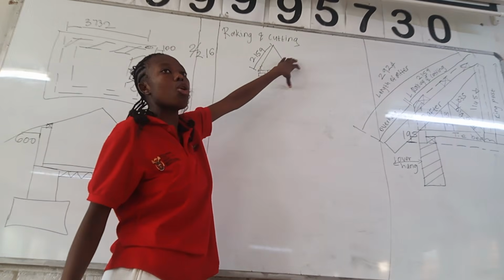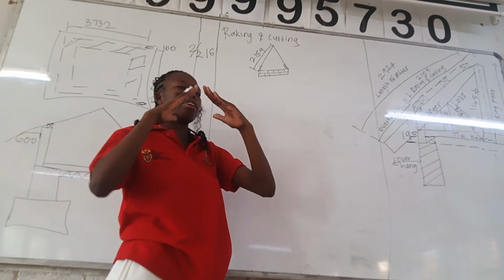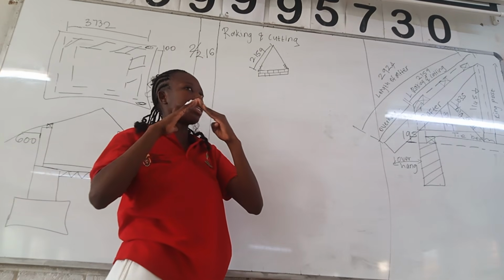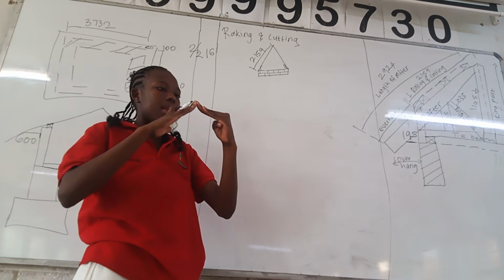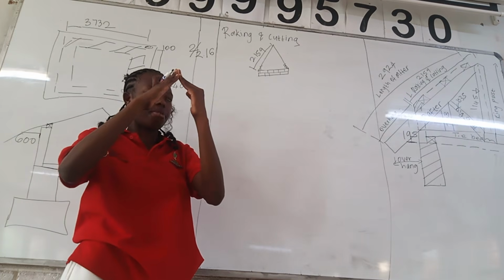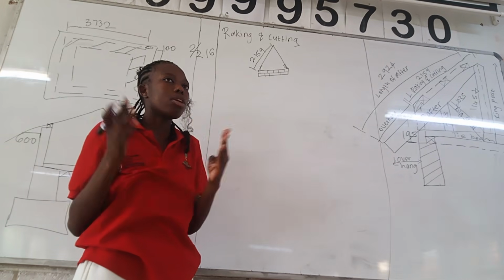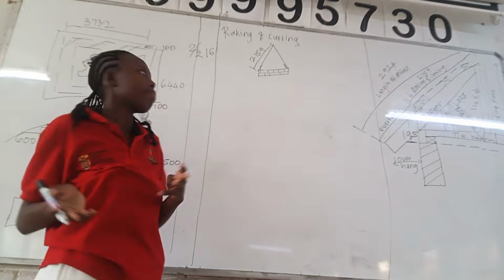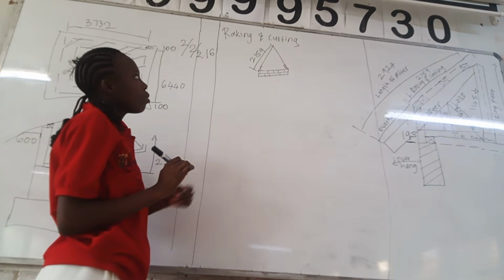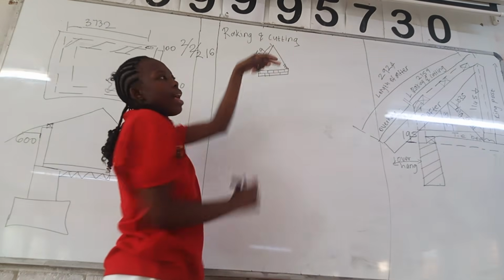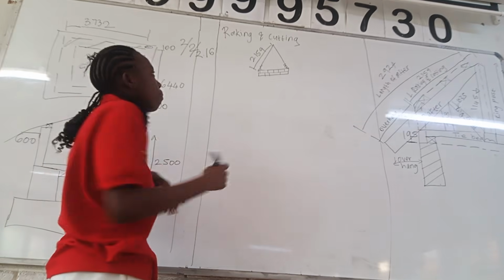And remember, this is only at the front. At the front, this is raking and cutting again. The 220 bricks are not fitting at the corners, so there's raking and cutting. And if there's raking and cutting here at the front, it means also at the back, since there's a gable wall, there's also going to be raking and cutting. So you need to multiply by 2. This 2 is for this side and this side, and the other multiplication by 2 is for the front and the back.